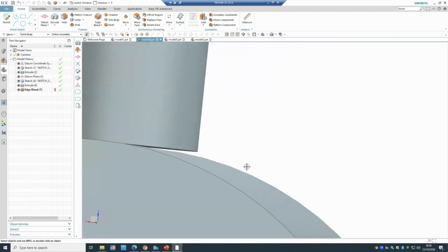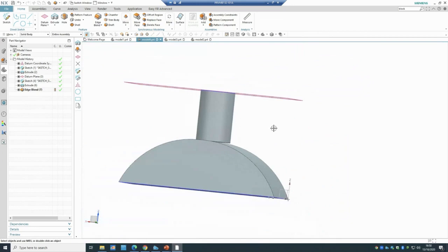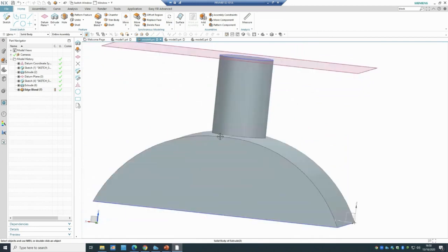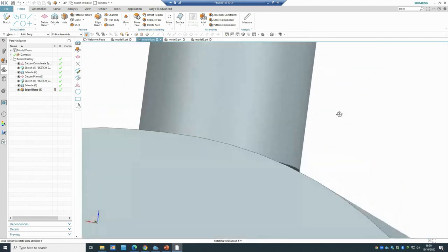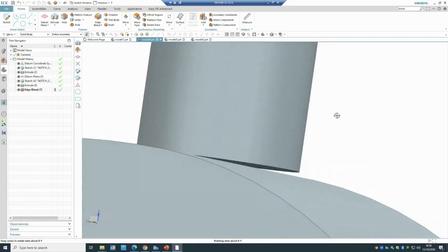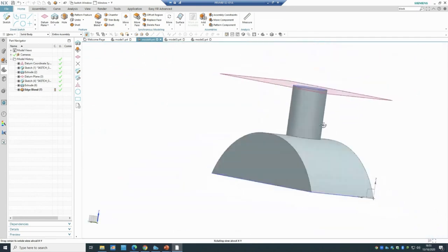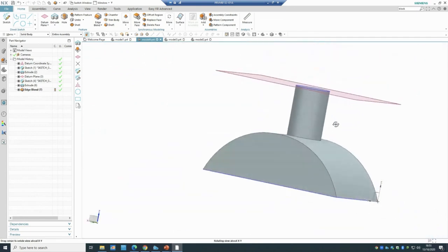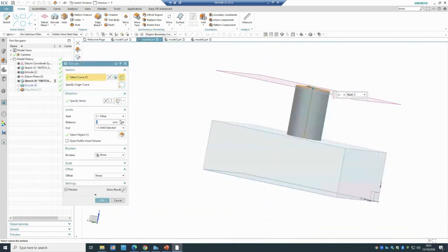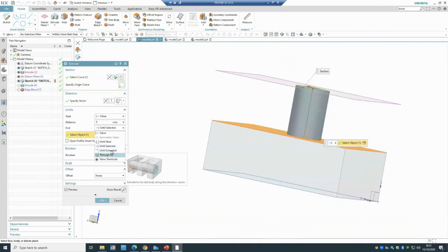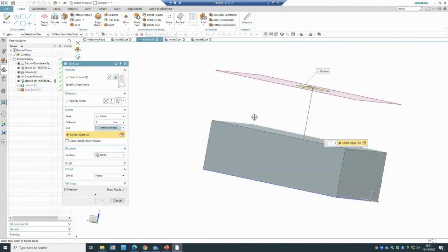It actually doesn't touch that surface fully. So you don't have the curve here because you just use the normal extrude, right? You see that? Okay, you have the gap there. So in order to get rid of that one, the method that I need to use for the extrude is extrude until extended. If I choose until extended, and I will pick this one,